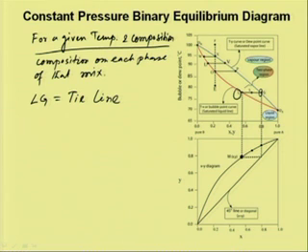So, we can draw an infinite number of tie lines in this region, and as I said, the point on the lower curve, at L, represents the saturated liquid, and the point at G represents the saturated vapor. The region below this red line, which is saturated liquid, is known as the liquid region, and above the blue line represents the vapor region, and the region between these two, the bubble point and dew point, is known as the two phase region.